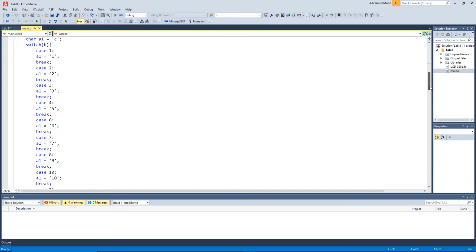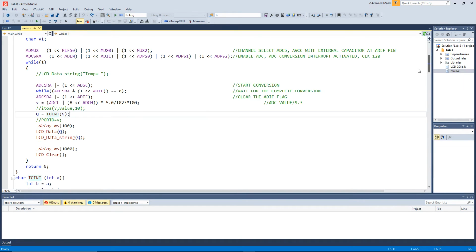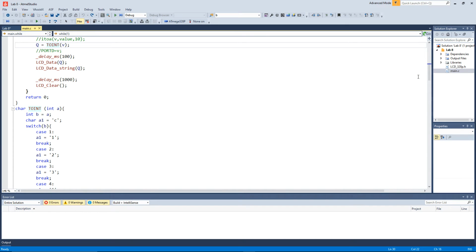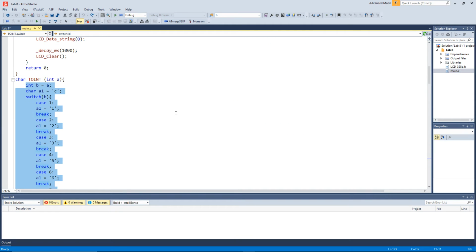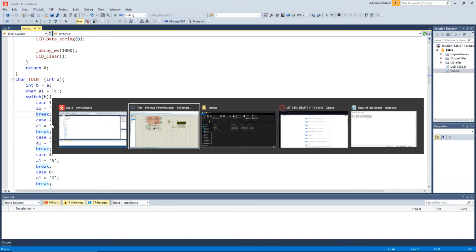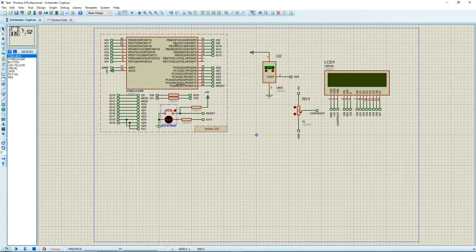As you know, sir, this switch case statement was written because our LCD was displaying some data which was not right. It was displaying the numbers in the hexadecimal system, so we wrote this function where we have written a bunch of numbers telling that if this number appears in hexa, you have to display this on the LCD. So I will just simulate it first to show you if it's working or not.